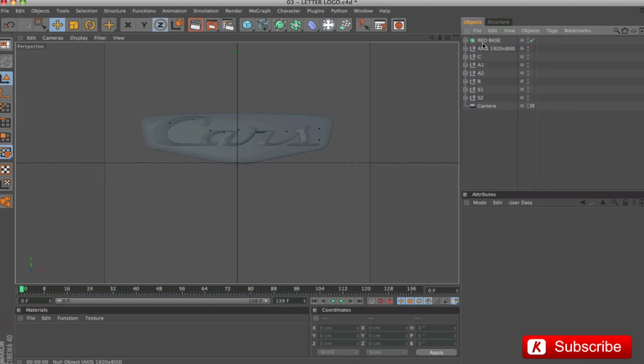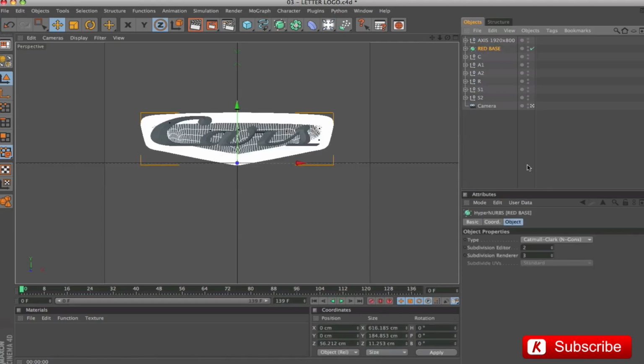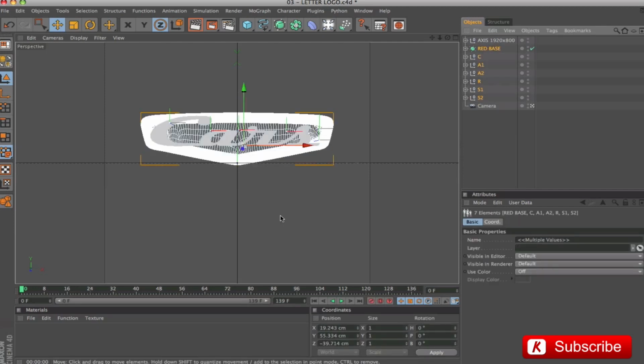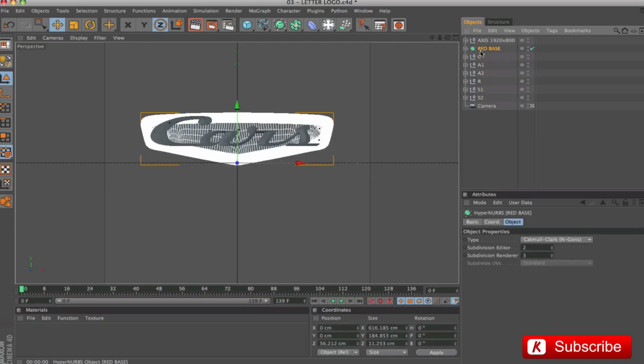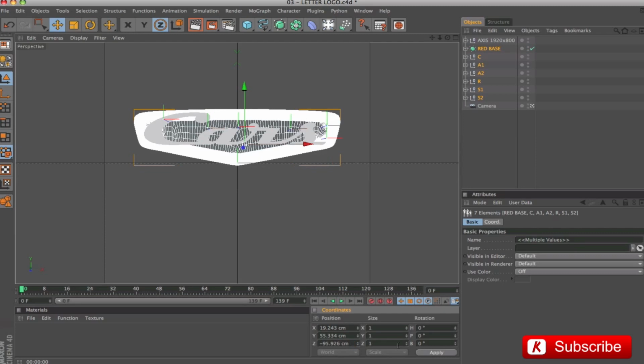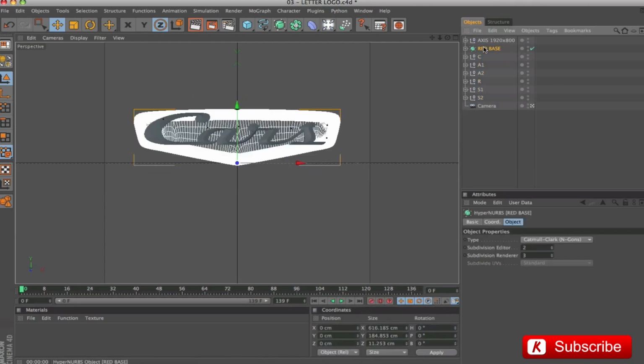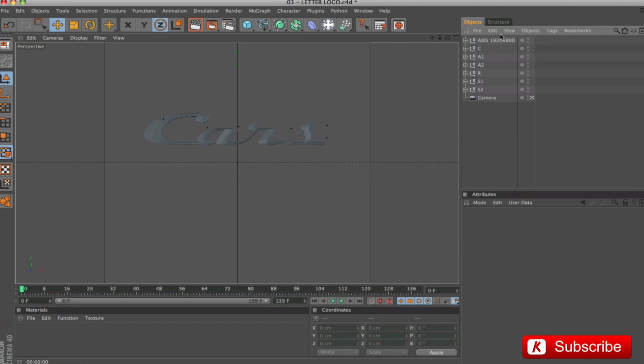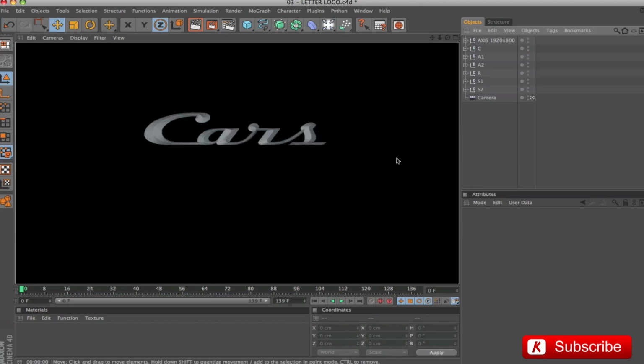If you remember, we have moved the red base behind the letters for the work of projection of the paths. We copy the z position value of the red base. We select all layers and paste it on the z position with the value negated. In this way a subtraction operation is made in the z position coordinate. The result puts the whole group of layers in the original position. Simple trick but always effective. Now we can delete the red base and rename the file with the suffix end.